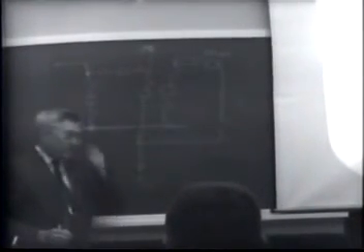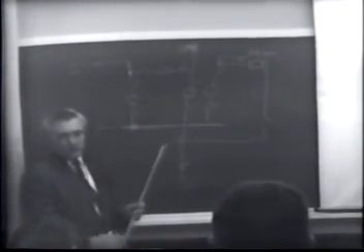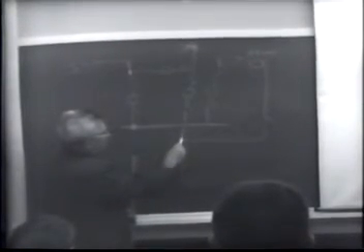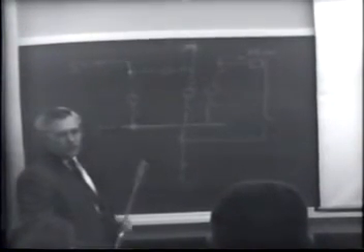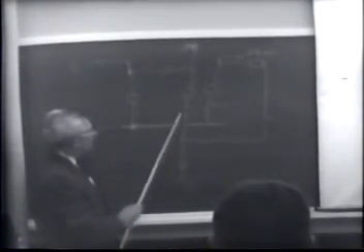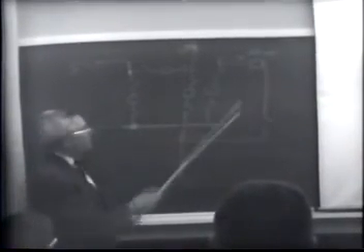Yeah, that's it. See? Could you repeat the question so we can hear it? Oh, the question was if the sub 56 line would be connected directly to a bus or if it would be connected through breakers. Is that correct? And it will be connected through breakers. This being a ring bus configuration, when the sub 56 line goes in service, you see it'll have a shared breaker with a Des Moines line on that side. It will have a shared breaker with the line to the north on that side. So there are the two breakers on the 56 line in the ring bus.